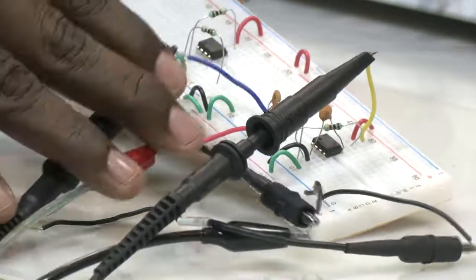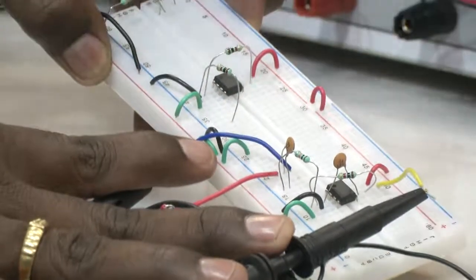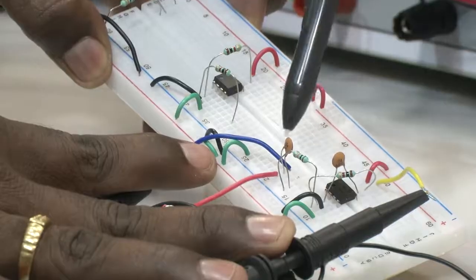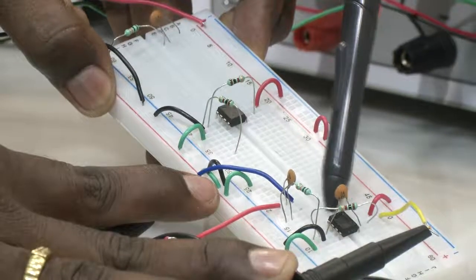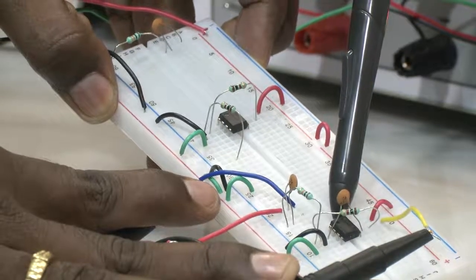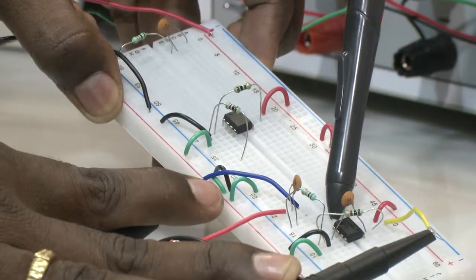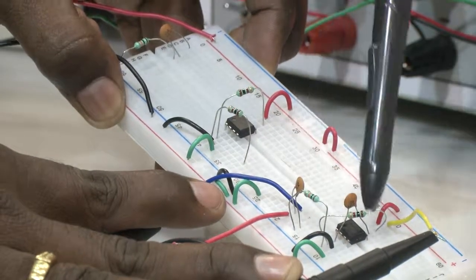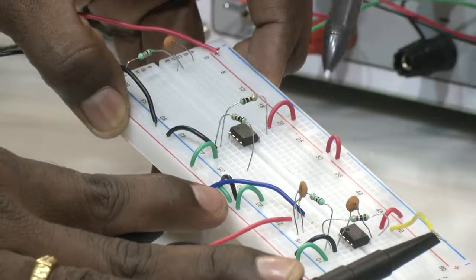Yes, a little bit more, yes, that is excellent. So, now what you see is, you have a high pass filter, you have a low pass filter, and you have the operational amplifier. Now you are using this operational amplifier in inverting mode, that is why the gain of this can be changed by using R1 and R2. By changing these, you can change the gain, alright.